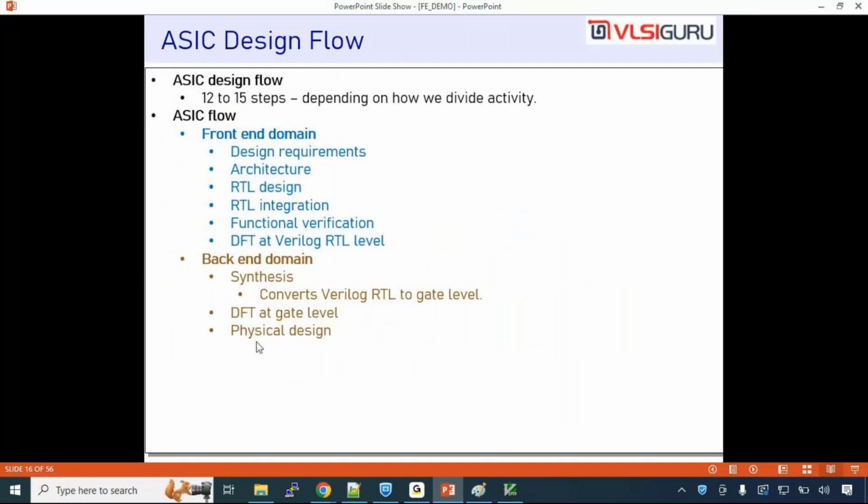Let's understand what exactly physical design is. Physical design means there are a lot of things in the chip, and all of them are going into a very small area. Millions, billions of gates going into a small area. The process of placing them, where to place what, is called physical design. Making sure that everything is placed, everything is connected, all the things are getting the voltage connections, all the things are getting the required clocks, is a very complex process. That flow is called physical design.